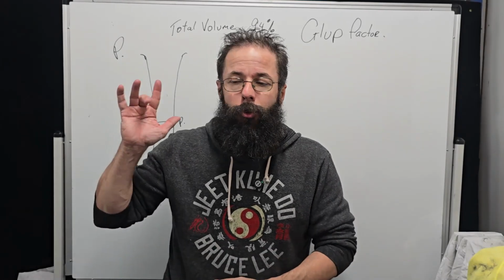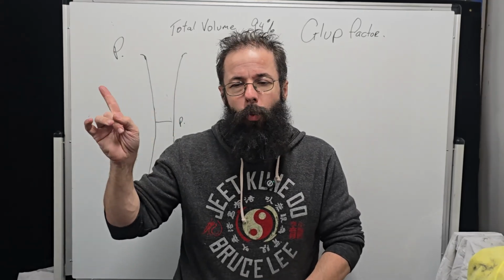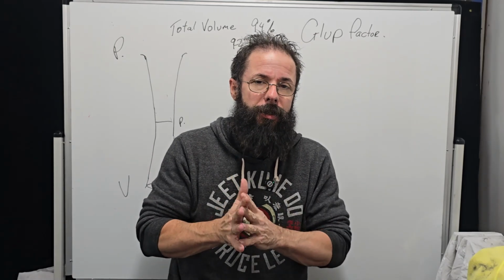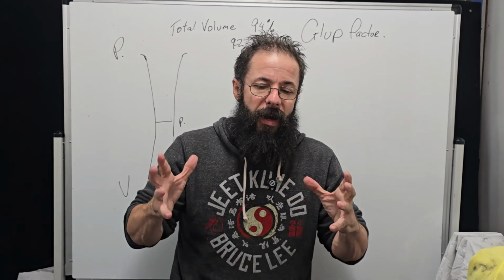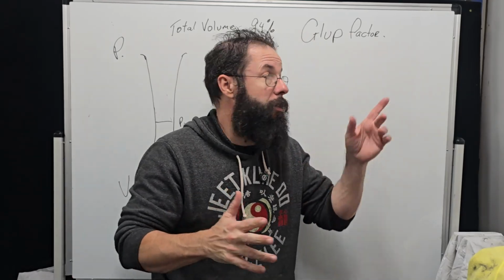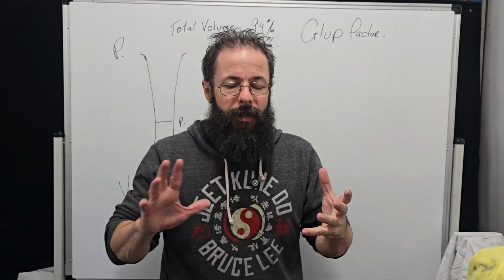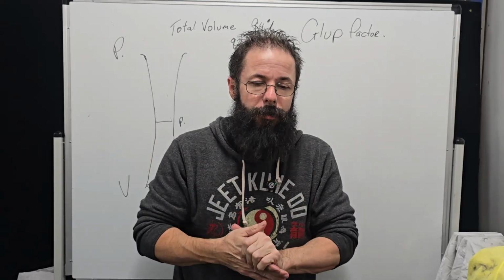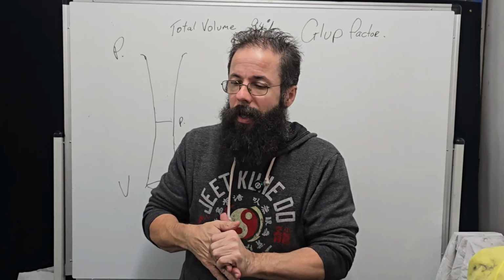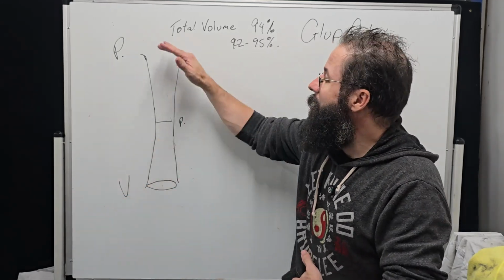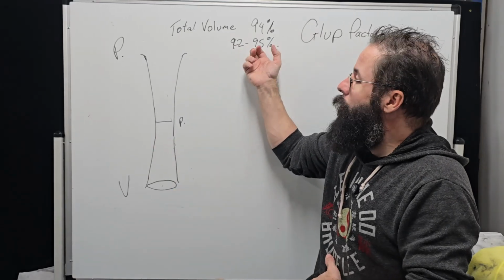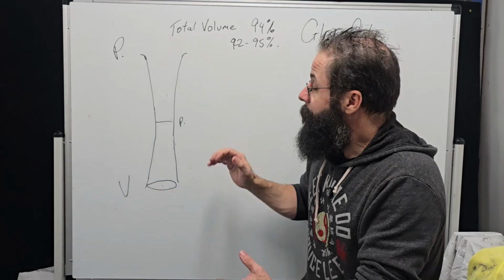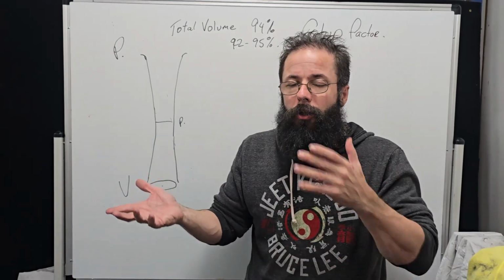All right, so we're going to lead into a bit of 4-valve stuff, but I thought I'd cover one other element in a really good induction system, a factor that I have termed the Gulp factor. Basically, that is how much air the manifold's going to drink, and this will lead into some of the calculators I'll show you now. That's basically the primary induction length having around 92 to 95% of the cylinder we're going to fill. So, that's why I call it a gulp theory.